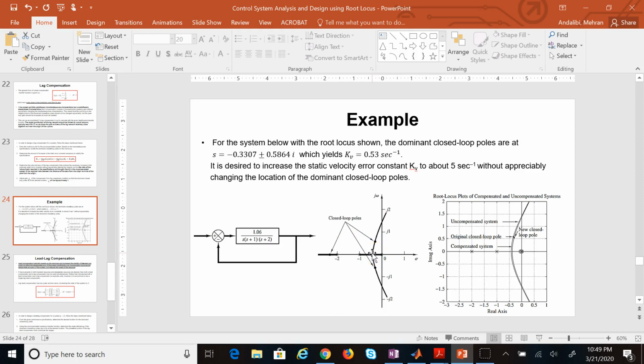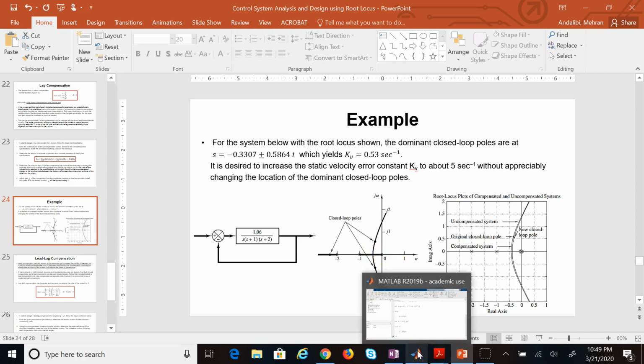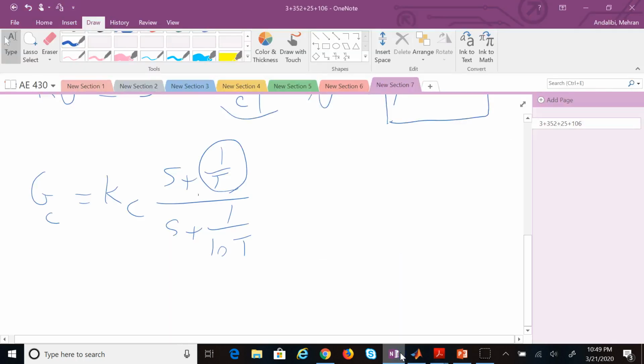But when this system has this breakaway point very close to origin, we want to push them as close as possible. Of course, not super crazy small, like 10 to the -8 or so. So if you look at your textbook, it suggested using this as 0.05. And so this one will be 0.005.